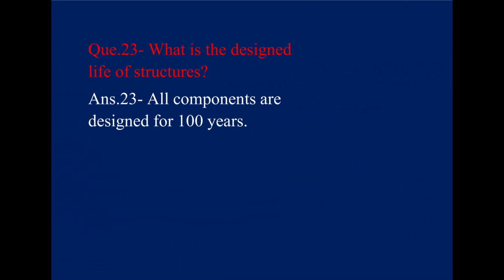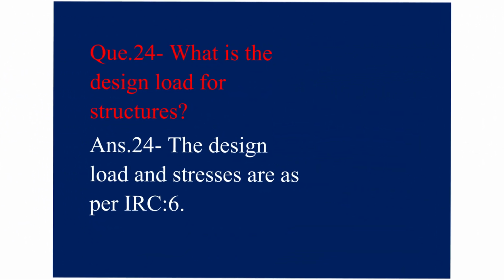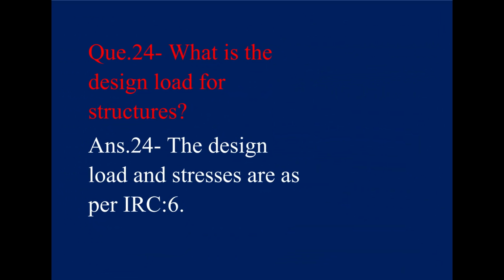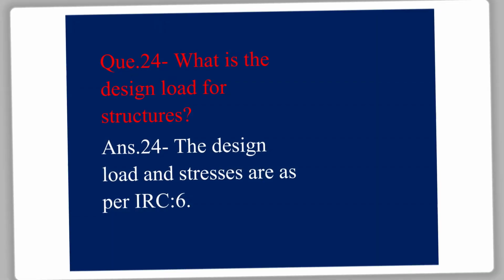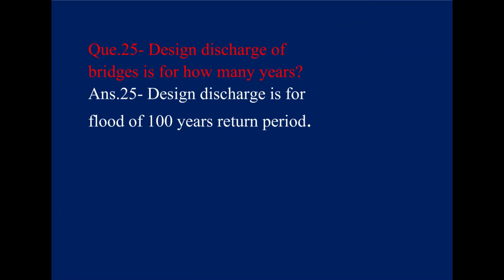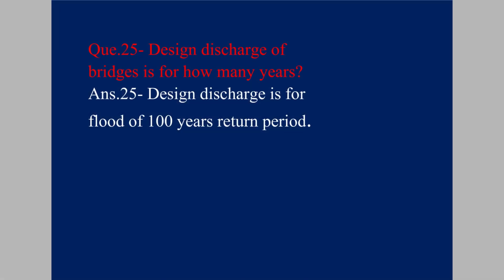Question: what is the design life of structures? Answer: all components are designed for 100 years. Question: what is the design load for structures? Answer: the design load and stresses are as per IRC 6. Question: design discharge of bridges is for how many years? Answer: design discharge is for flood of 100 years return period.